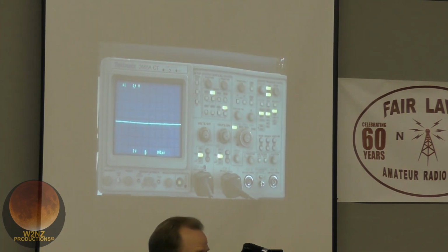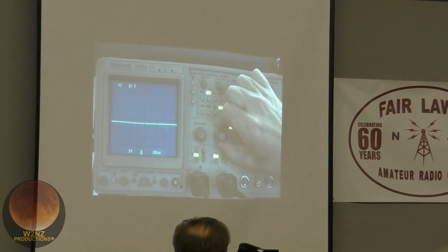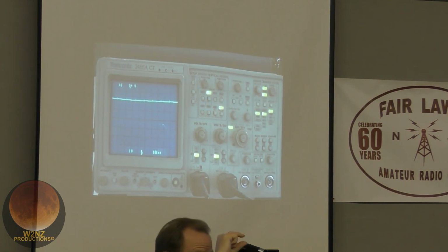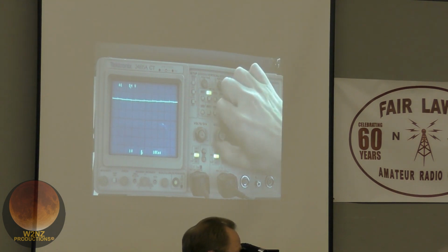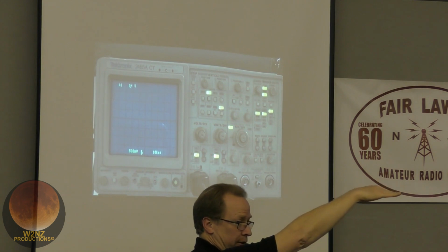You can see there's a little bit of ripple on that signal. But what if I want to look at that? I'll change the sensitivity of the scope to say 1 volt per division. See, now the signal's up there. I'm starting to see it a little better. I made it more sensitive, but now it's up towards the top of the screen. Let's go down another click. Well, 500 millivolts per division, the trace is up here somewhere, right?